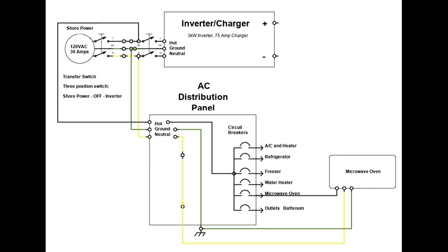All of your outlets and switches should be rated the same as the overall circuit. So if you're using a 15 amp circuit breaker and your switches and outlets are 15 amp on that circuit, don't throw a 20 amp one in the mix. Typically, a separate circuit is used for each larger load. However, one circuit can power multiple outlets, commonly called convenience outlets.